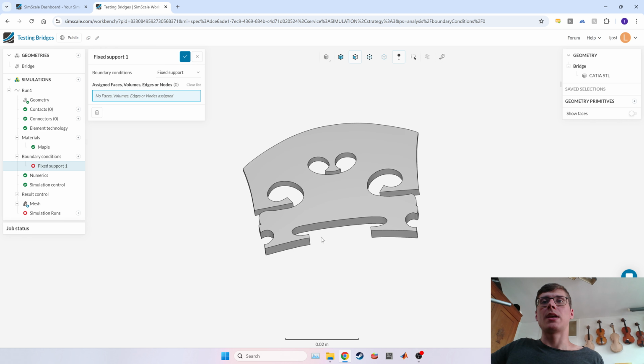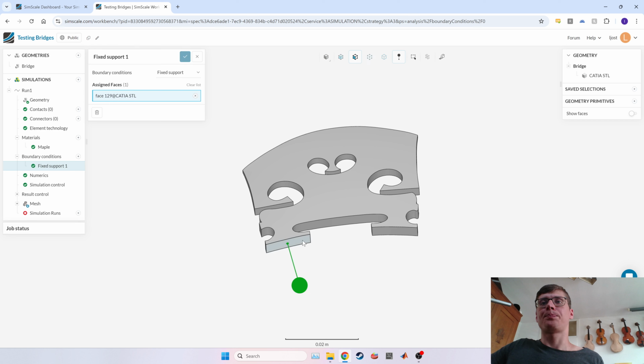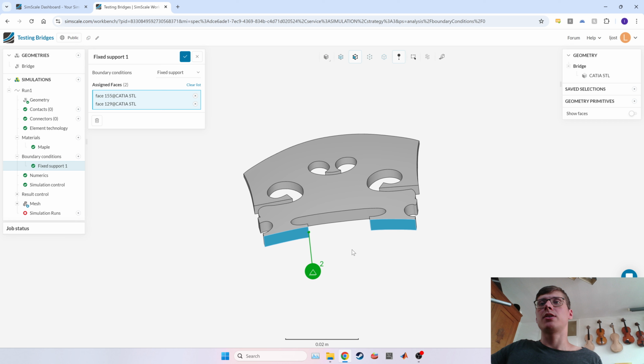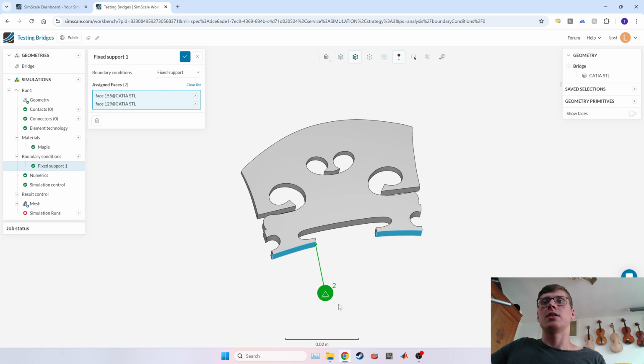In this case, we're just going to simplify a little bit by clamping these faces. These are easily accessible to us. Yes, we cannot represent this measurement really well in real life, but since we know it just pushes up the frequencies by 200 Hz, we still can get relative comparisons.